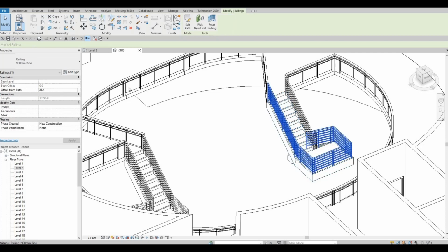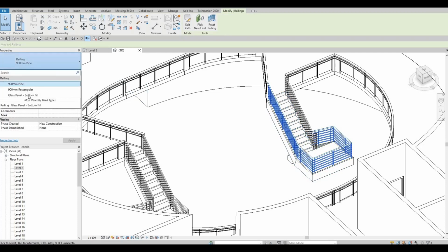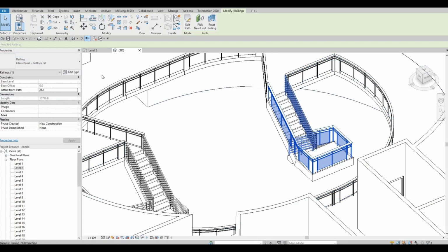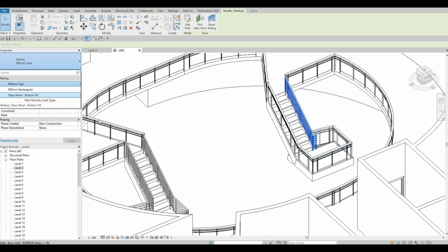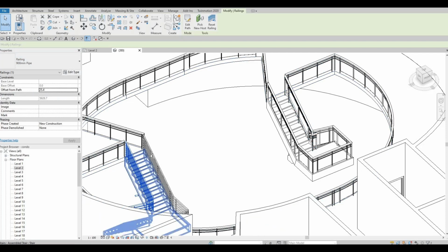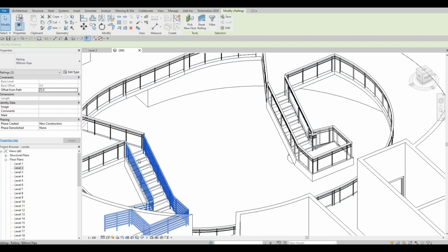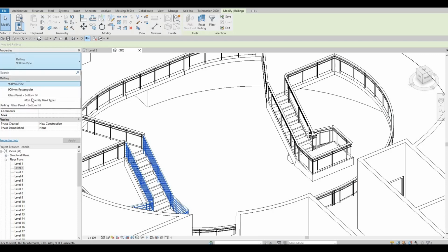And also we're going to change the railing. So here you just need to select the railing and then click on class. And then here as well, let's select both of these by holding the control button and then changing it right here.